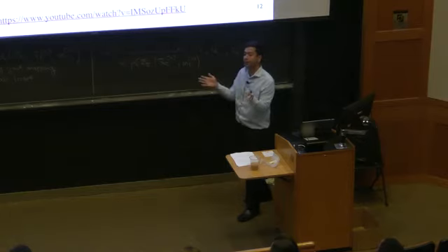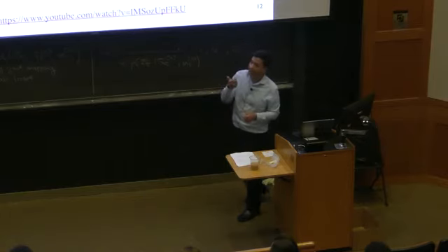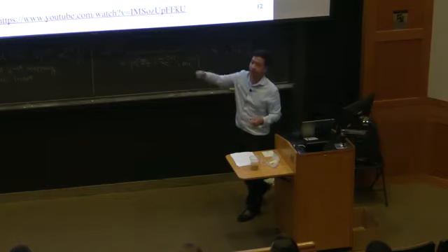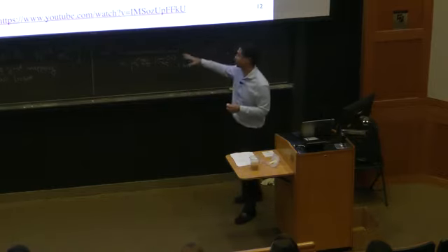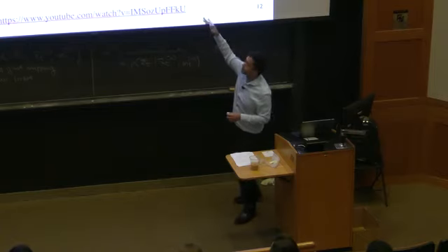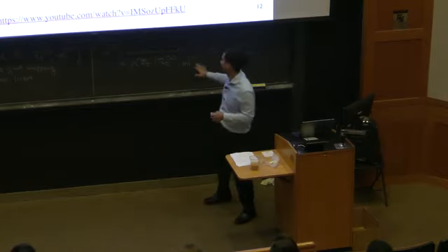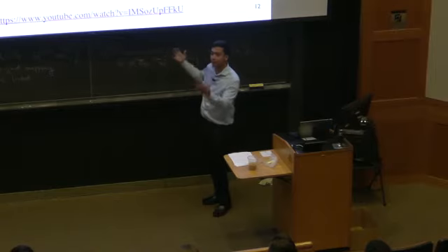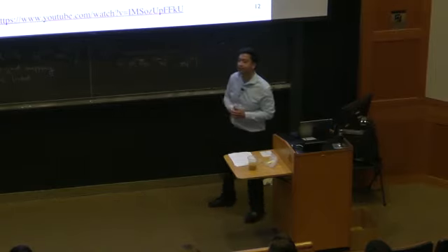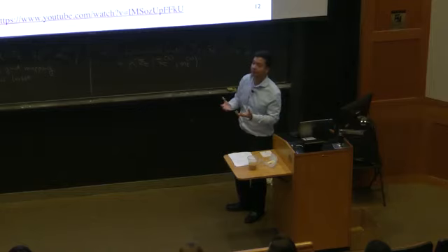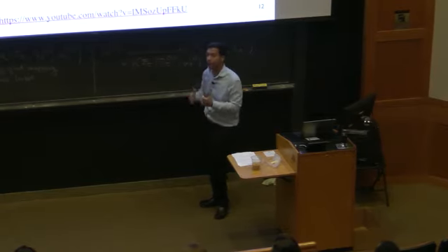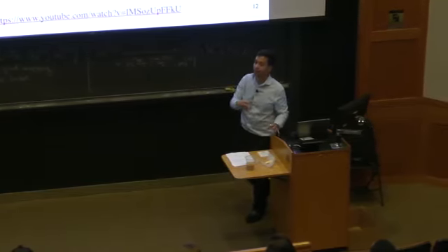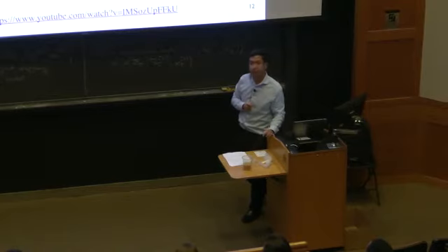So if your robot has a range sensor, you can characterize those error probabilities, like the probability that your range sensor sees an obstacle that's not there, and the other probabilities, and get a measurement model that way. So in the algorithm that I described, we're assuming that this is given to us. In practice, of course, we would have to go and do a bunch of experiments on our particular sensor to come up with a probabilistic model corresponding to the measurement model, and then plug that into the particle filtering algorithm.